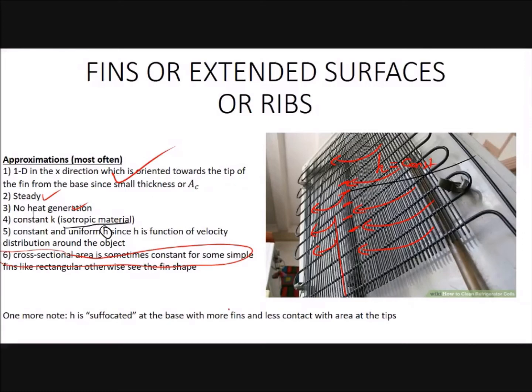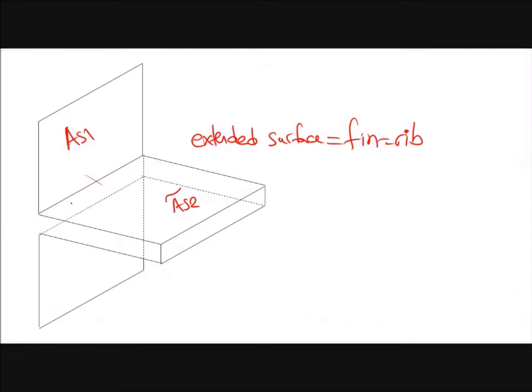So we should have the optimal number of fins. If there are lots of fins, say that you have one fin here, another fin very close to that one, another fin very close to that one, this is not good. Why is it not good? Because now air cannot enter in between the fins. If air cannot enter in between the fins, then the convection heat transfer will drop.